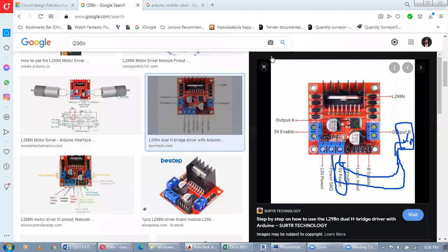For the Arduino, what pin do you have to connect? Maybe digital, analog, or PWM pin? These are signals, but they are not analog signals. They are digital signals. We give 5 volts or 0; in-between voltage is not necessary. That means two values, the higher value and the lower value.